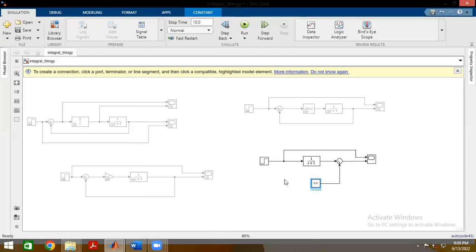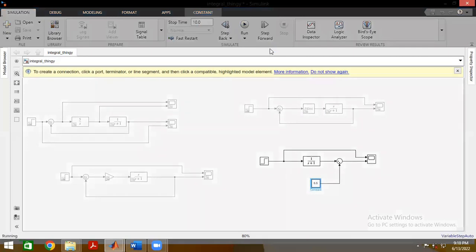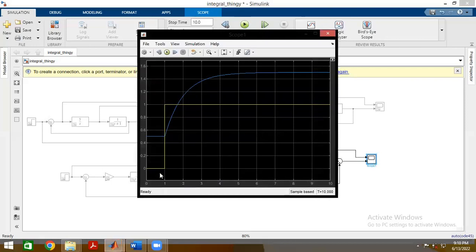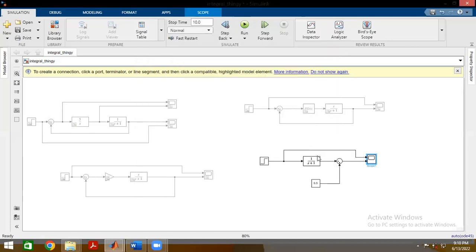Right, so now if we introduce this disturbance in this system, let's see if we still track the reference waveform as accurately as we did before we had a disturbance. The answer is no. This is our reference, but this is our output. So the output is 0.5 volts off. That's not right.